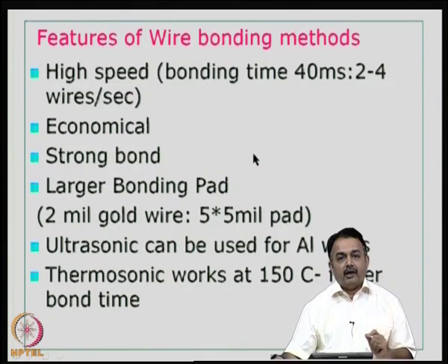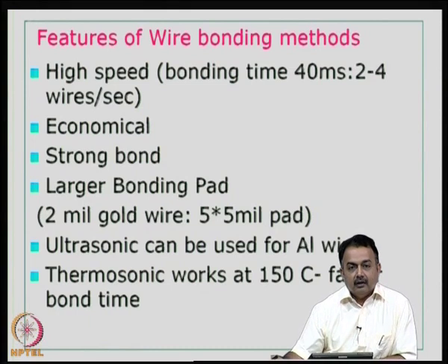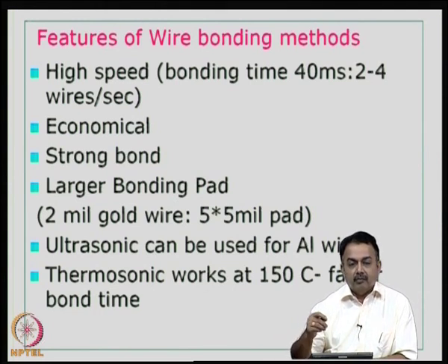So, you can see that the wire bonding process in the industry depends on high throughput. Typically, we are looking at something like 60 to 70 hits or wires per minute. So, it has to be very fast and it has to be accurate, and all the processes have to be in tandem. If it is a ball bonding process, the formation of the ball, the formation of the loop, and then the stitch bond at the other end should occur in perfect tandem and without any misalignment.